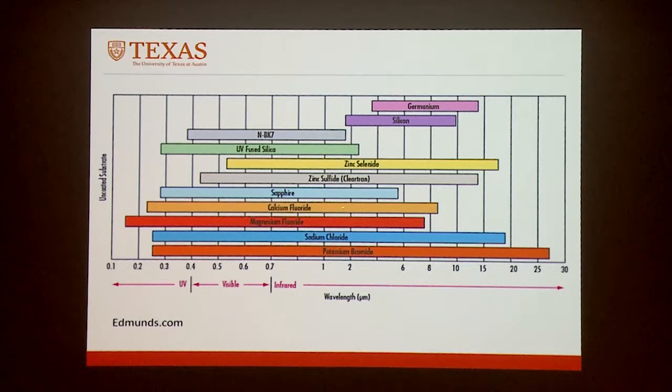There are a lot of other materials that have various ranges over which they're usable, and as a result, as you go from the optical to the near infrared, then out to beyond 2.5 microns, your choices in what you use for transmissive materials change. This means you have to rethink what you're doing with the instrument, and in particular, when you're building an instrument that covers a very large band from 1 to 5 microns, say, your choices become very constrained. And this often drives you to using reflective optics, where you don't have a problem with material transmission, rather than using transmissive optics. But this is a factor that comes up.